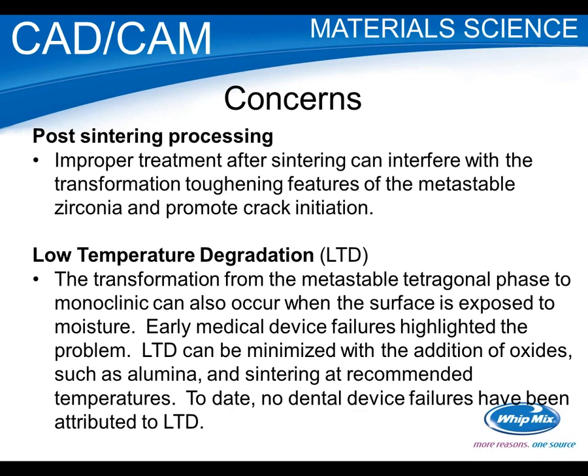And what they found is that depending on the additives to stabilize the zirconia, even at room temperature or body temperature in a humid environment, some of that moisture would interact with the surface and actually convert some of the tetragonal to the monoclinic. And now if you get crystallites swelling at the surface, they're going to pop out and spall, and then it gets progressively worse. And they've addressed that mostly.